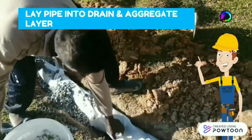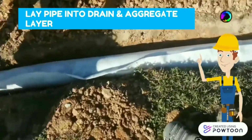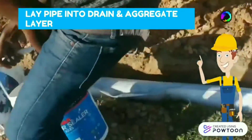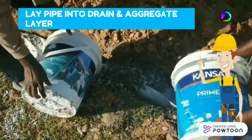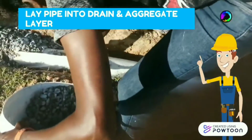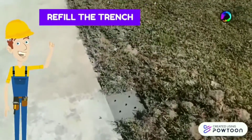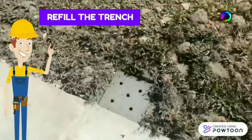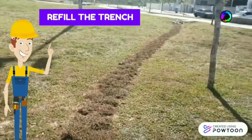And then lay pipe into drain and aggregate layer. For proper performance, the filter material or backfill should usually surround the drain, under as well as over. However, this will depend on the nature of the strata being drained and the depth of drain. And the last one is refill the trench. Once all the piping has been laid and you have confirmed there is a steady downgrade for the whole length of the system, we should fill the trench.